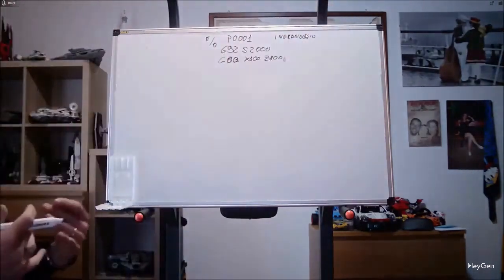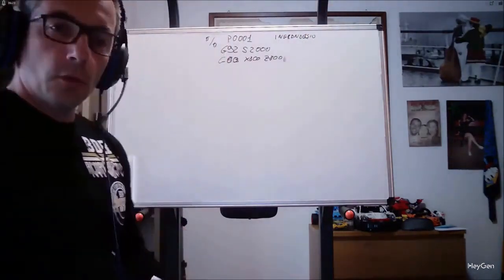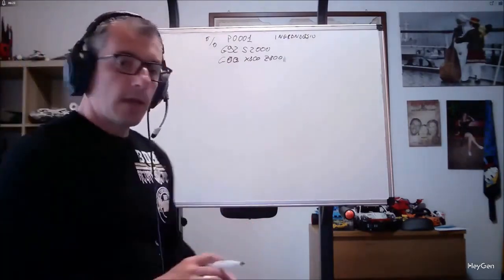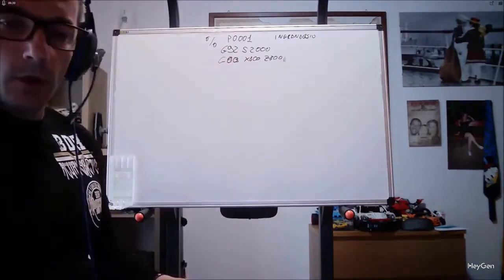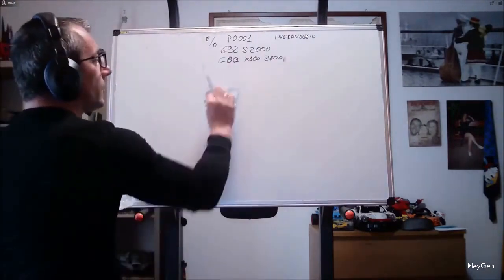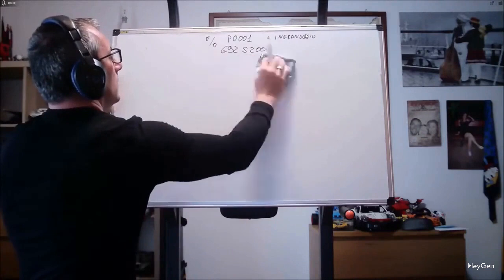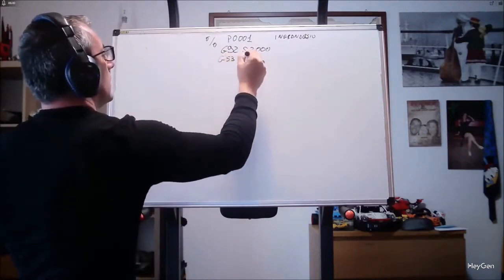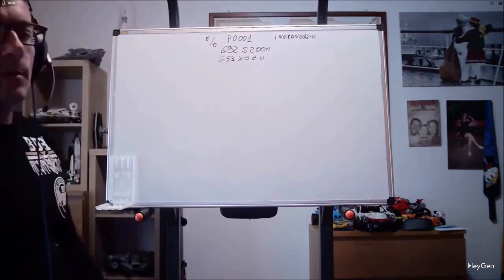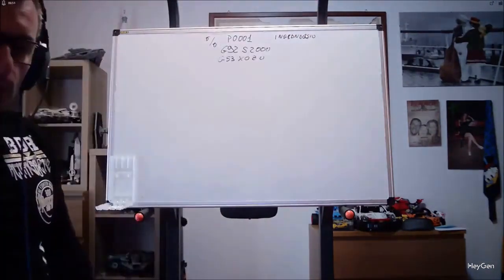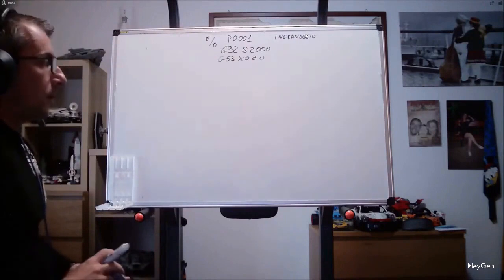I foresee an approach to the first movement block, first in Z and then in X. I will explain this too. I don't define this as important, but know that if you find it, especially on Fanuc, I remember this well. G53, X0, Z0 tells the machine to go to its origin point, which is usually high and far from the spindle.